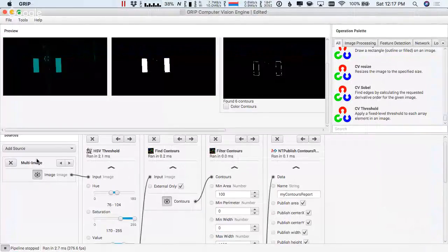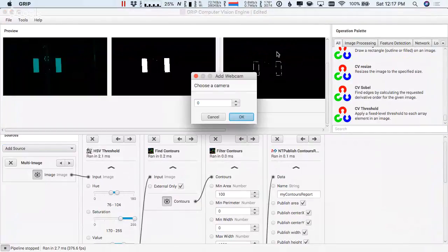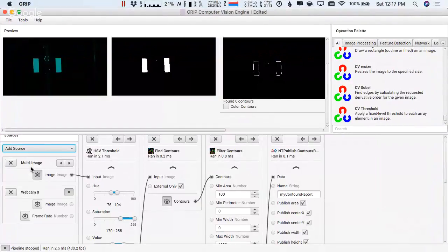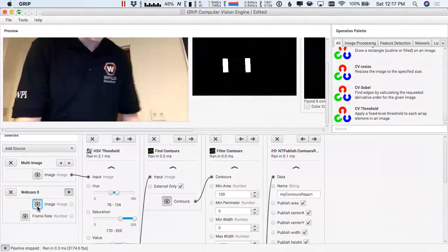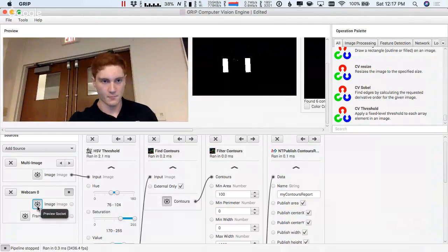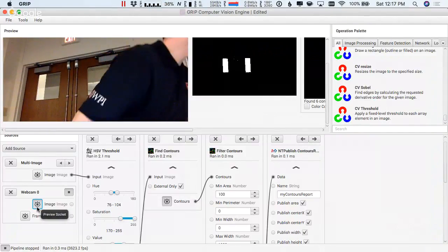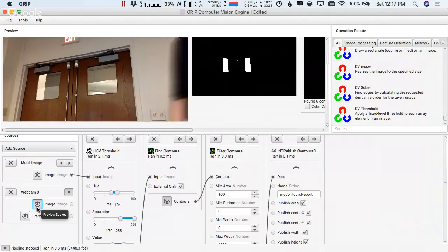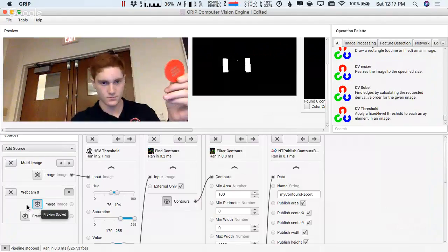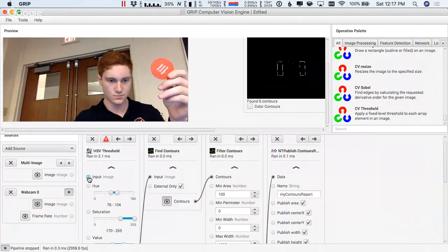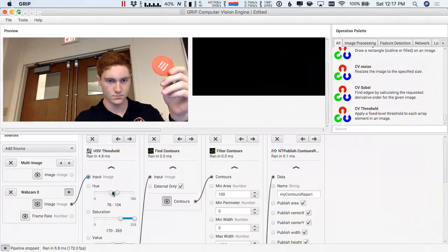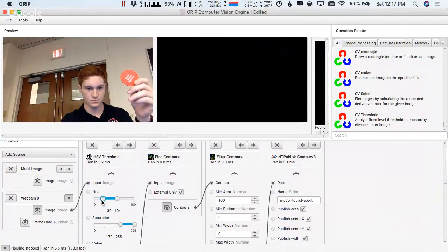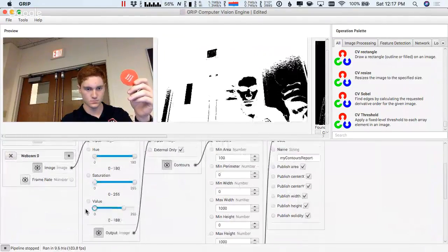In your robot program, you say get X, get Y, and then you get those values. See over here? He's just publishing, and you can choose what to publish. You can publish the area, the center X, center Y, or there's a whole bunch of other stuff that's down here that you can't see. Publish or write to NetworkTables. And then the program in the loop just reads those numbers from NetworkTables instead of from the camera.